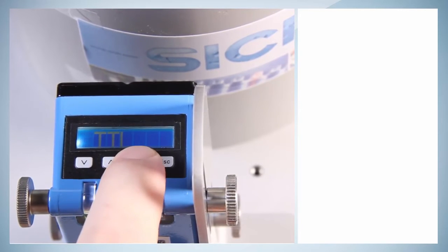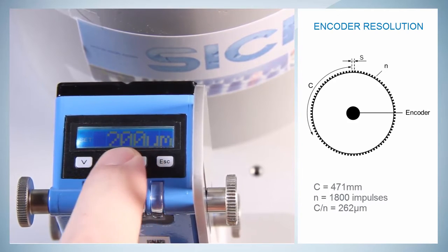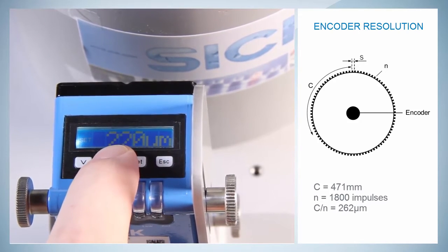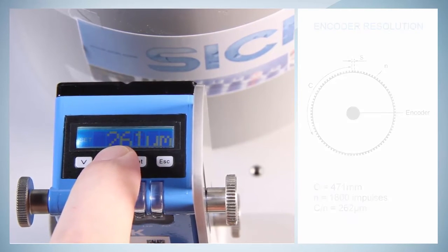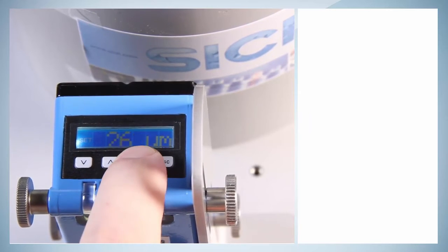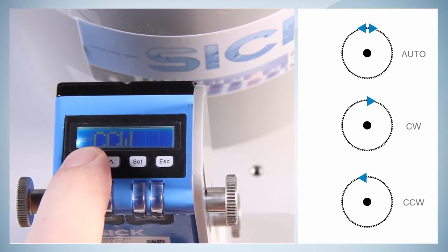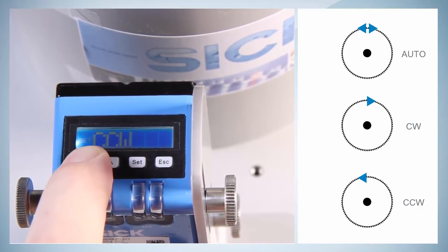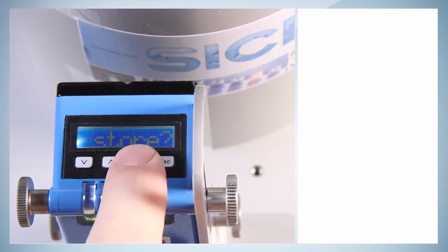The encoder resolution can be calculated as follows. The circumference of the drum is 471 mm, which shall be divided by the number of encoder impulses per rotation. In this case, it is 1800 impulses. The resulting resolution then is 262 microns. The encoder direction decides between automatic direction detection, a clockwise or counterclockwise encoder direction. These values have to be confirmed before getting back to the main menu.